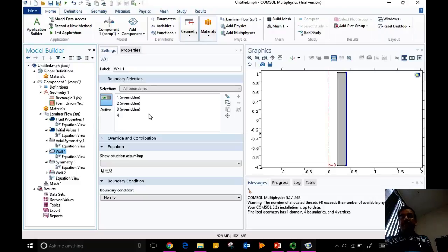But in the literature, people have studied, including Taylor, two cylinders that are rotating in opposite directions, two cylinders that are rotating in the same direction. All these are possible. Here is a question for you to think about. If both are rotating in the same direction, at the same angular velocity, what would you expect the fluid to be in between? Have a profile. So we'll have that 1D profile, with moving conditions at both the walls.